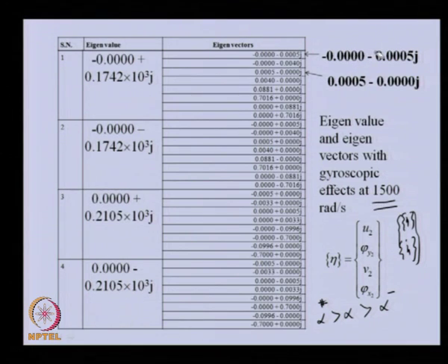This is because they are corresponding to two different planes. One is horizontal plane, vertical plane, they have 90-degree phase. So, we expect them to be 90-degree phase, and then eigenvector also. And another observation is we are getting the purely either imaginary quantity or real quantity, because there is no damping in the system. So, that is why we have this particular typical behavior of the eigenvector.